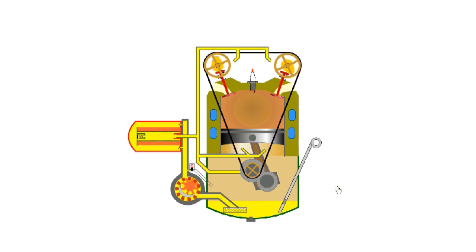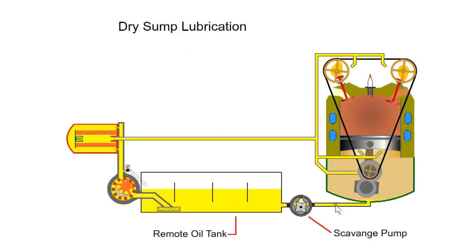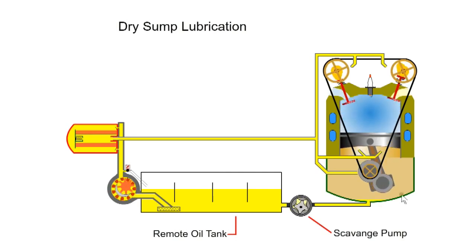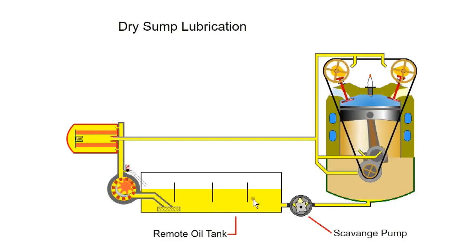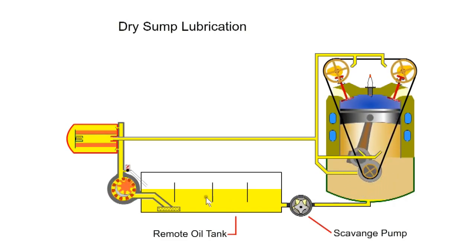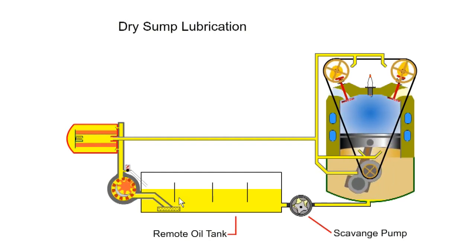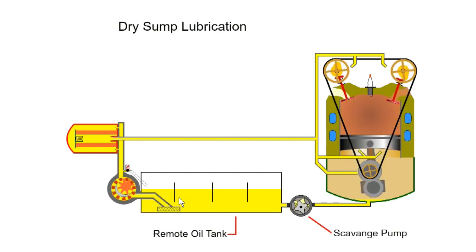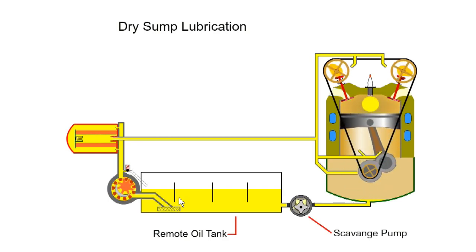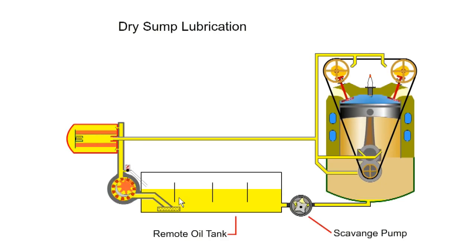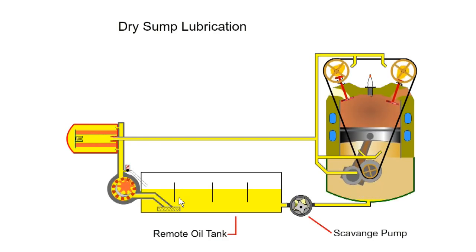Some cars, such as high-performance cars, have a dry sump, which has an external reservoir which is not located under the engine. The engine can be moved down, providing a lower centre of gravity. Oil is kept away from the rotating crankshaft, and the sump itself can be any shape or size. An additional oil cooler can be used which operates similar to the water cooling radiator and prevents the oil from overheating. On modern cars, electronic analog measurements are used to monitor oil pressure and level. Oil quality can also be monitored, and the engine control unit alerts the driver when an oil change is due.